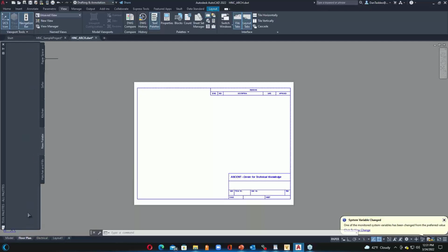I can customize this. And because of the AutoCAD options that allow me to define where the tool palette file is, I can put this into a shared directory that everyone can populate the same tool palette from, just by pointing AutoCAD to that file.